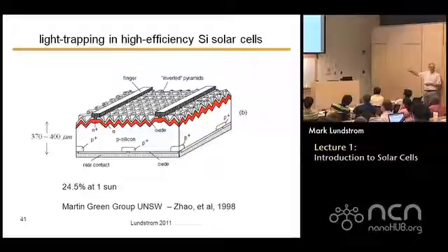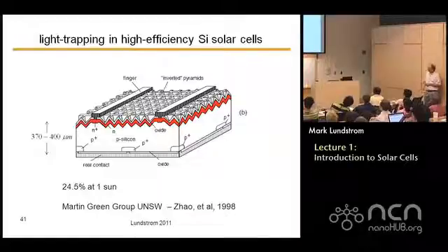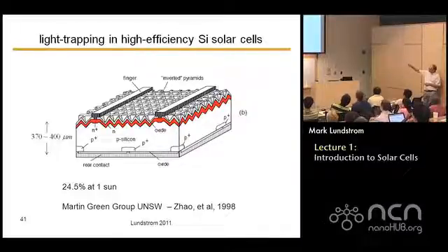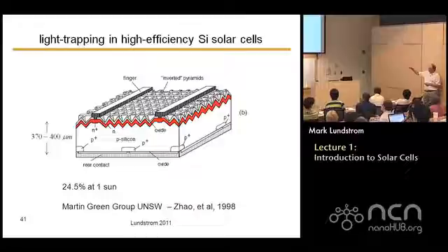It's got a chance to get transmitted there. So it has a very low reflection coefficient. Once the light gets in, if it goes all the way to the back and it hasn't been absorbed yet, you can see that on the back surface there's a thin layer labeled oxide. That oxide layer is about a half wavelength thick, so that when the photons go down, reflect off the metal back contact and come back, they interfere in phase.